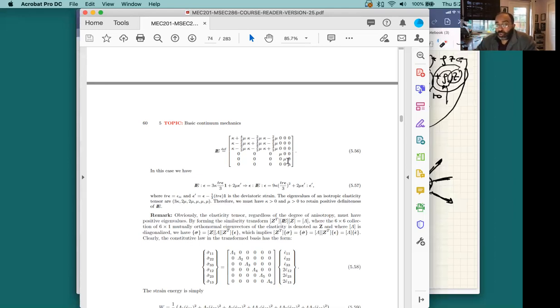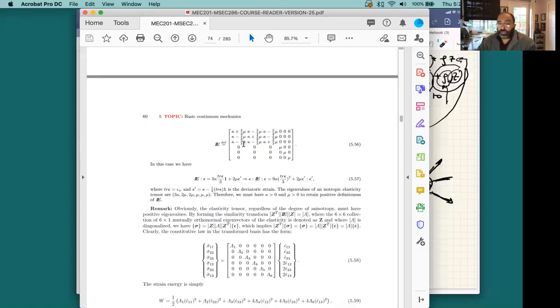Isotropic materials have two material constants that need to describe every one of the 6 components in the constitutive law of elasticity. The two that are most common in the scientific literature are the bulk modulus and the shear modulus, and there'll be some reasons for that, as we'll see later on today in class. But they primarily represent the shearing response, which is represented by the value of mu, and the bulk response, which represents the amount of volumetric compression that a material has.